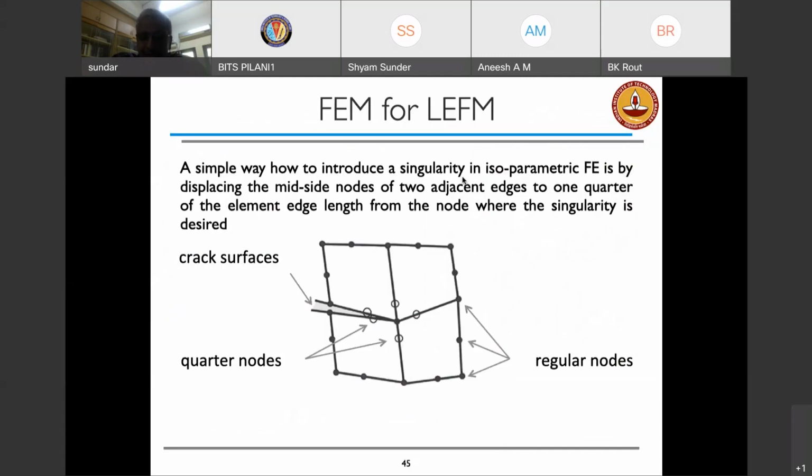So in terms of linear elastic fracture mechanics, we know that if there is a crack, there is a singularity at the crack tip. And the conventional finite element method with polynomials cannot capture the singularity. So one way to do it is to use higher order elements, in particular what is called a quarter point element, where we move the mid-side node close to the crack tip so that, because of the mapping, you end up with a singularity that can be captured. But this is difficult if the crack starts to evolve, merge or branch out. Meshing becomes a nightmare.